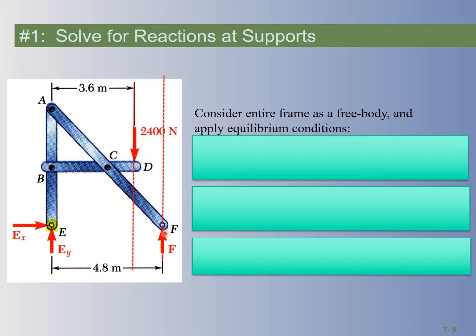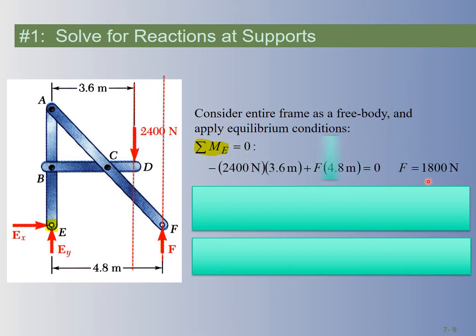And then we have the external forces applied at points E and F. Okay, so how can we solve for EX, EY, and F? Remember, the easiest way to solve these is with a moment equation. The most unknowns are happening over here at point E.